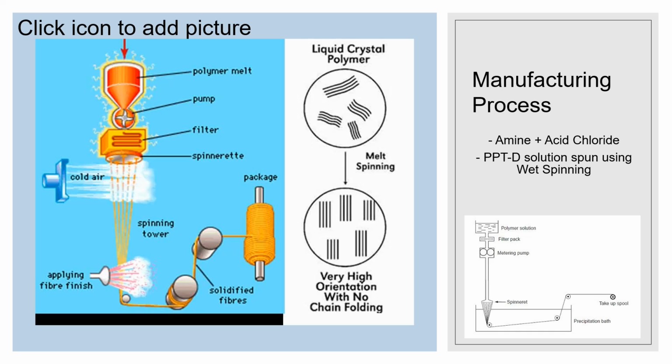The bath allows the polymer solution to precipitate and form protofibers, which are then pulled along several rolling pins to be air dried and hardened into filaments. At the end of this process, the spools of fibers are cut or woven and then treated for their intended application.